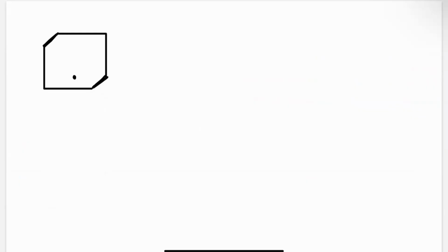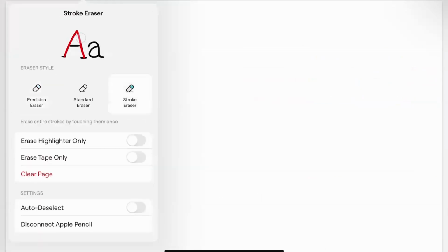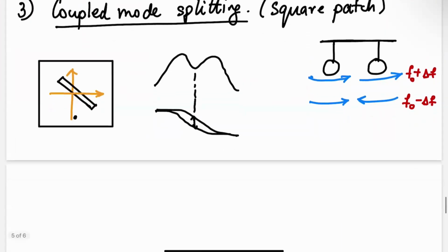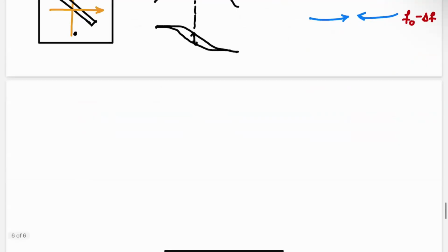Those are the different techniques used in making circularly polarized patches. There are more. We use square and rectangular patches, but you don't have to do that. You can use a circular patch and make that resonate at two different frequencies and try those kinds of things as well. If you make elliptical patches, you can make all kinds of shapes. But at some point we have to say, okay, we've covered the basics, and then you can go ahead and read the literature and come up with your own designs.